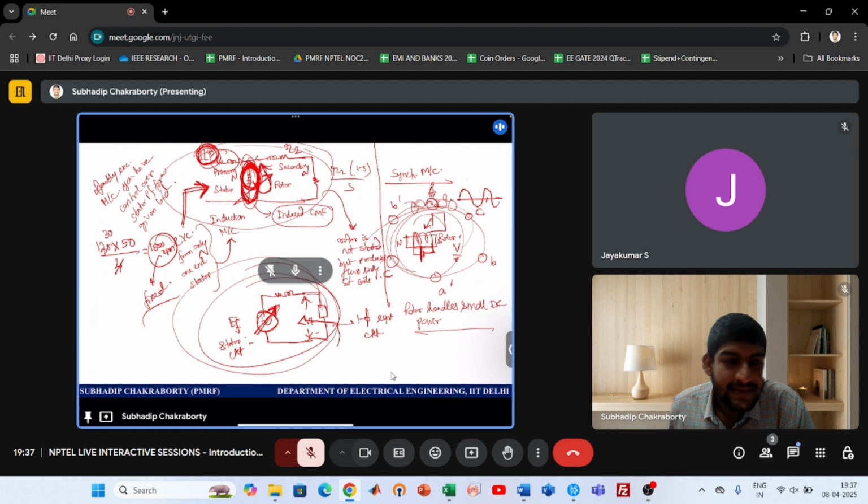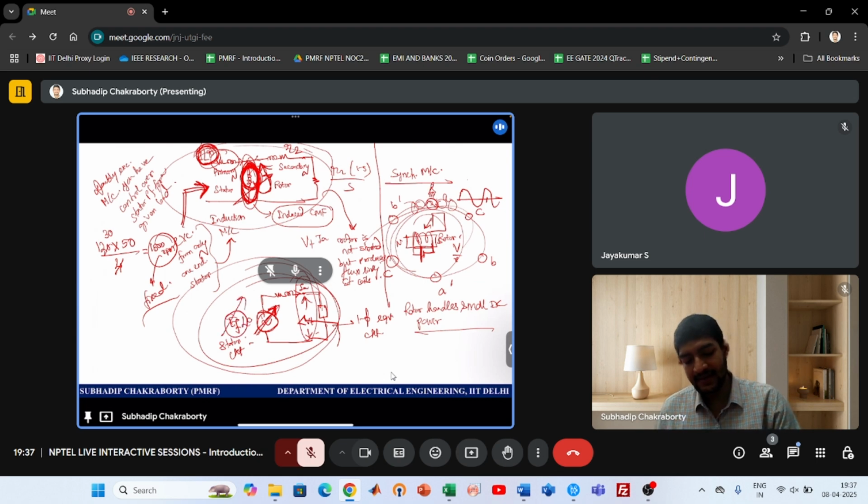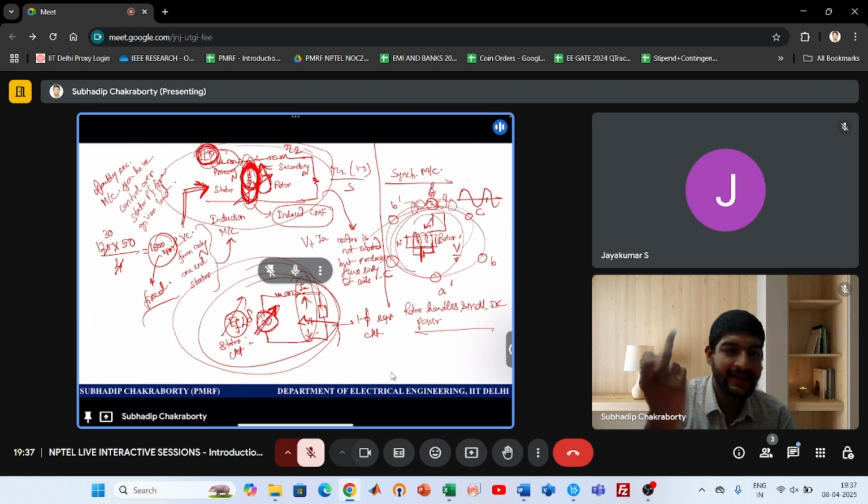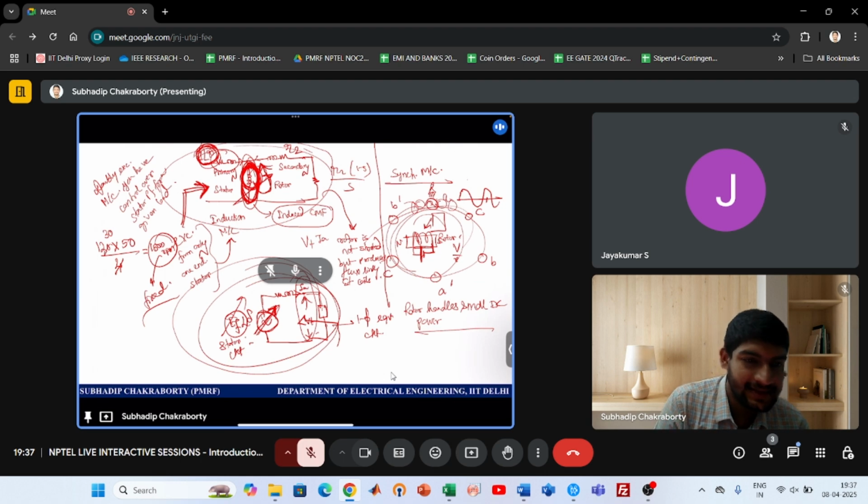So what I am telling is, even if I power some reactive loads, I can control my excitation to ensure that my stator power factor, that is the power factor between terminal voltage and stator current, this voltage is VT, this is IA, this power factor becomes unity. I can do it. How can I do it? By changing the angle and the magnitude of EF. So I can vary the excitation and accordingly I can push the same amount of power but at a better power factor. That is the magic.